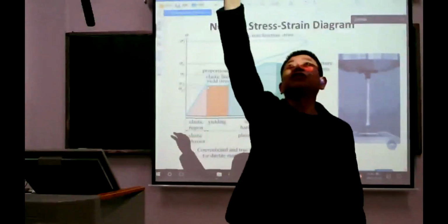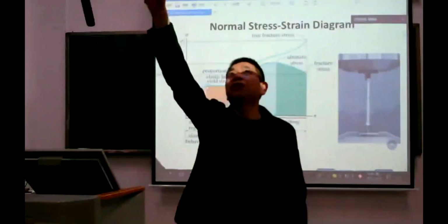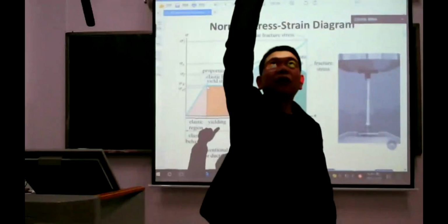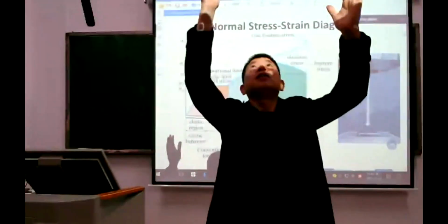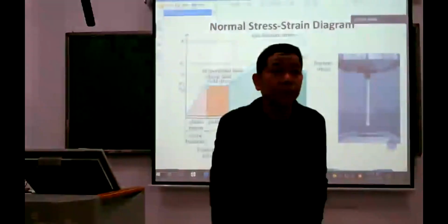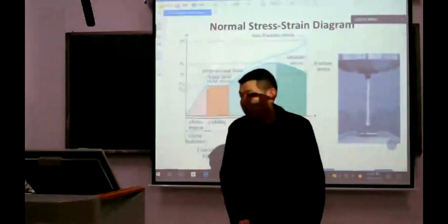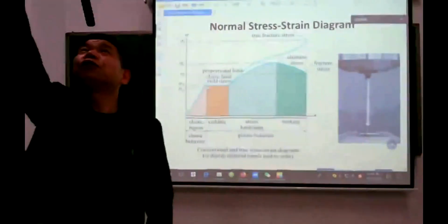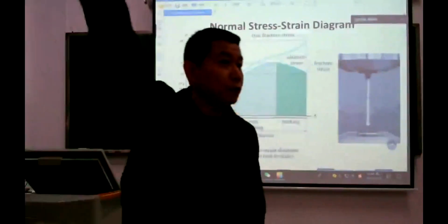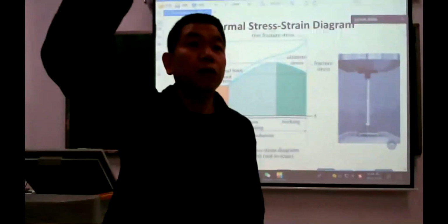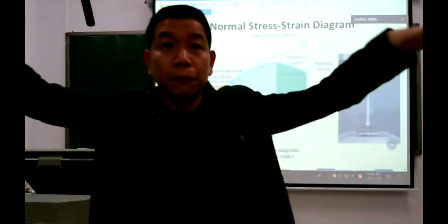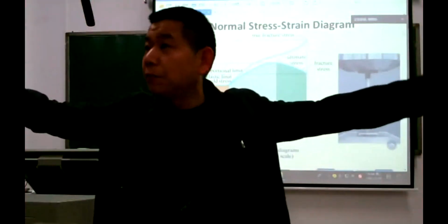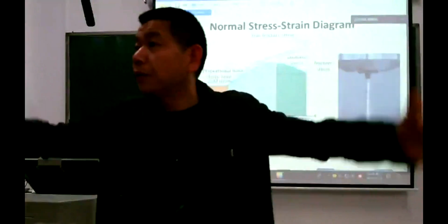Most of the steel rod is on the bottom part, in the mid section. For the beam, most of the steel rod will be arranged on the bottom part of the beam and in the mid part of the beam,